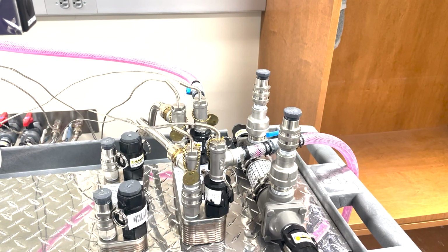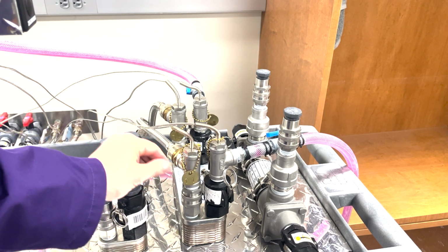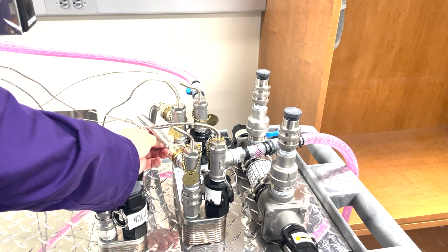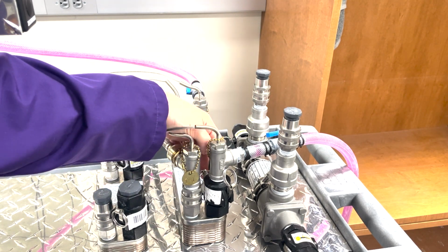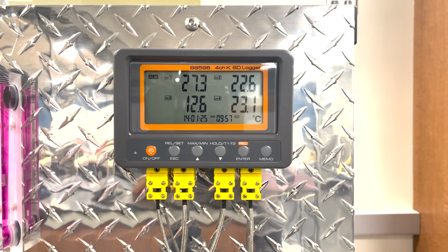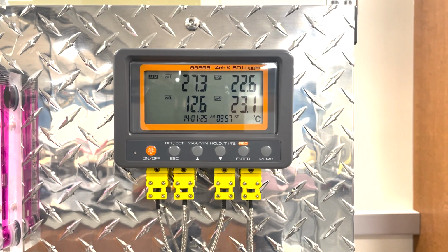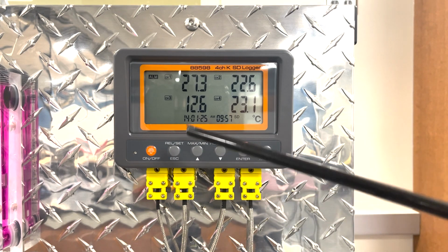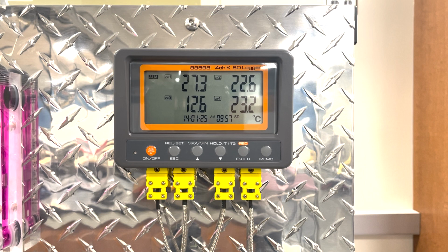Four temperatures are measured in the experiment. The brass tags identify these as T1, T2, T3, and T4. The two top temperatures on the meter are for the hot side inlet and outlet streams, T1 and T2. The bottom two are for the cold side inlet and outlet streams, called T3 and T4.